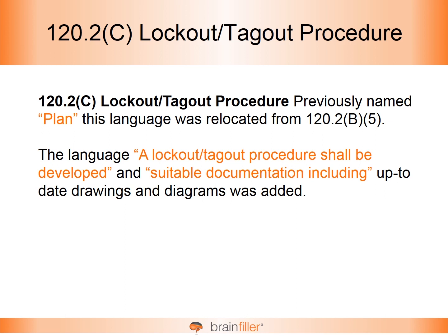If you go to a site, and I've done this before, and you ask, do you have an electrical one-line diagram? Some places will have a diagram. Others look at you like they're not really sure what you're talking about. And then you get to the point about, is it up to date? Well, it was up to date in 1977. Yeah, that's not quite what we're looking for. So part of this may actually be bringing drawings up to date to reflect whatever the current conditions are.